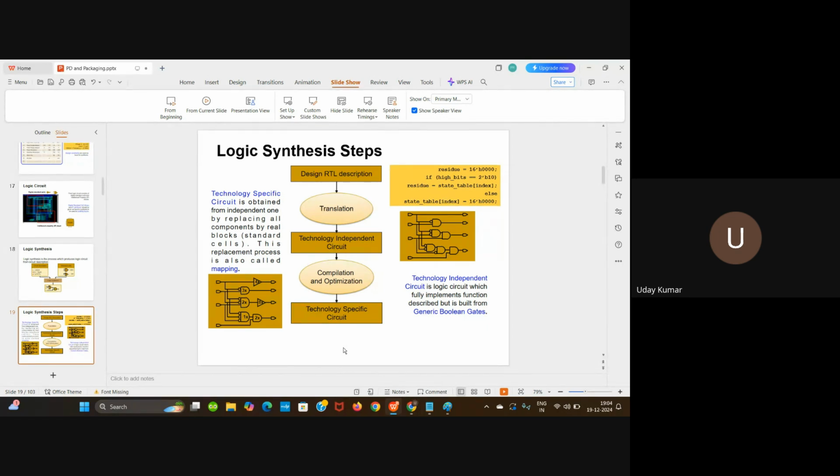There will be standard cell layout engineers, and they will be providing all these gates. They'll be providing the area information in the form of LEF and timing information in the form of the Lib. So while you're doing the logic synthesis in the first stage, it is called generic synthesis. The tool will insert its own generic gates. So you might not be able to make out the area and timing with those generic gates.